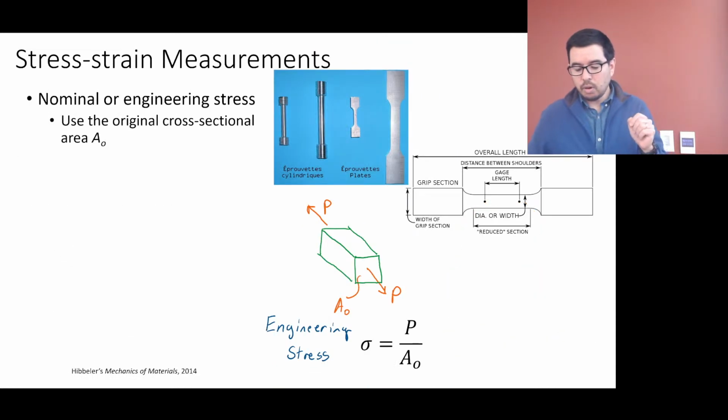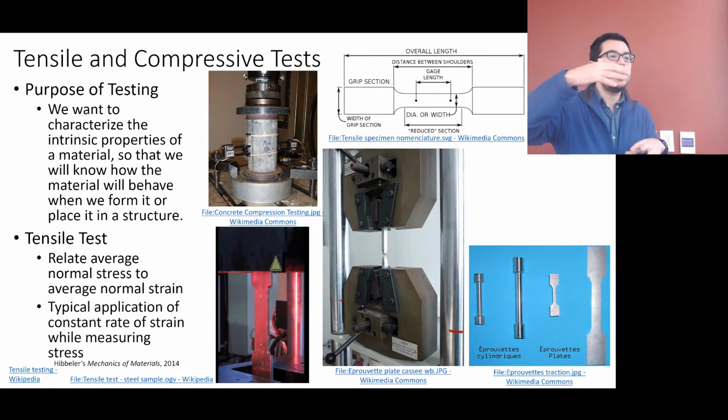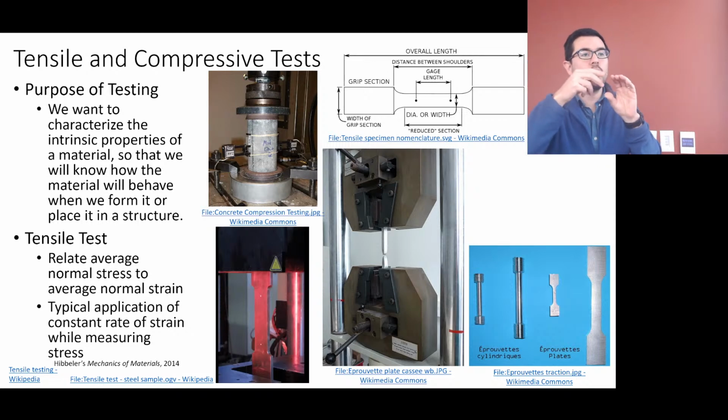Those machines are pretty large, and they need to be able to handle high loads in some cases, but with their size, they also have the ability to flex or stretch some. And so what you want to do for more accurate measurements, or measurements with high accuracy, is have the extensometer either contacting the sample directly, or you have a camera that's looking at the sample directly and you're measuring the distance between 2 points on that sample.